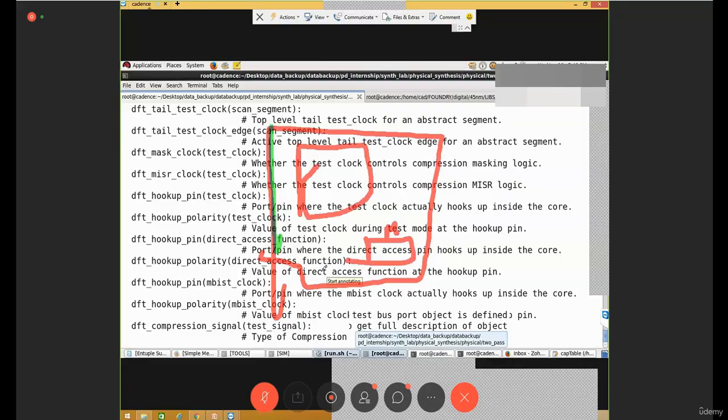This particular block could be coming from some other company, or even directly from the foundry. When I am considering the physical design and even the synthesis, I don't have access inside this particular block. This is called hard IP. For this hard IP, to see what the power and other information is, I get it in the form of the LEF file.